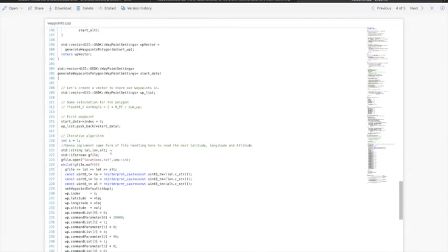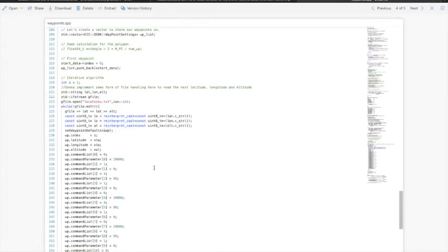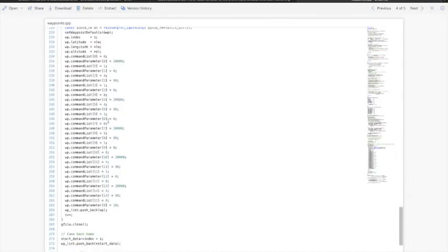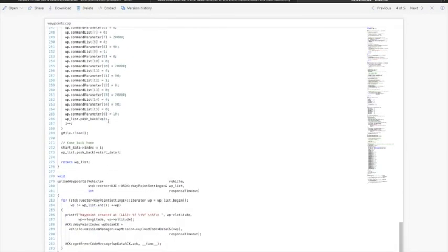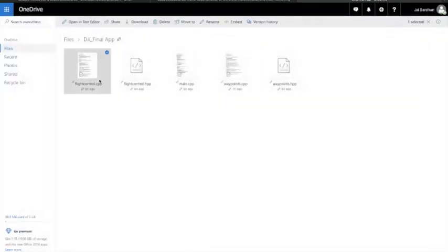After which we have used this algorithm to develop the path, and we have saved it as a file. The inputs are read from the file, and it's saved as waypoints onto the drone. Now each waypoint has a certain action attached to it, and here we have set the order so it would first stay at its location for 20 seconds, then take a photo, turn towards the left by 90 degrees, and then take another photo, and then again stay at its position for 20 seconds, and then again turn 90 degrees until it has completed one rotation, and then it will move to the next waypoint.